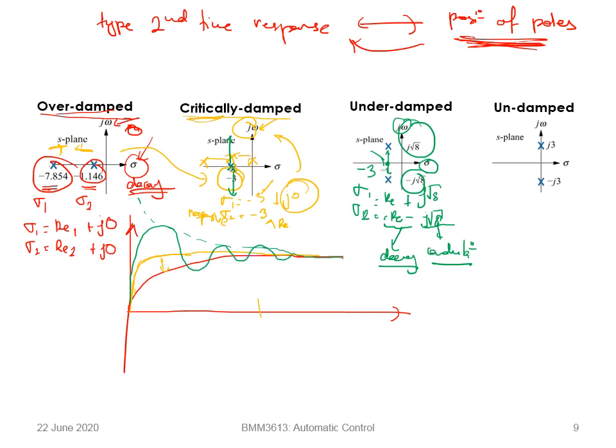From the yellow signals, now it has become the green signals. So it is faster, of course. You can see that it increases to the value of the steady state faster, with a smaller t, but it has what we call an overshoot. It overshoots the steady state value and it undulates.